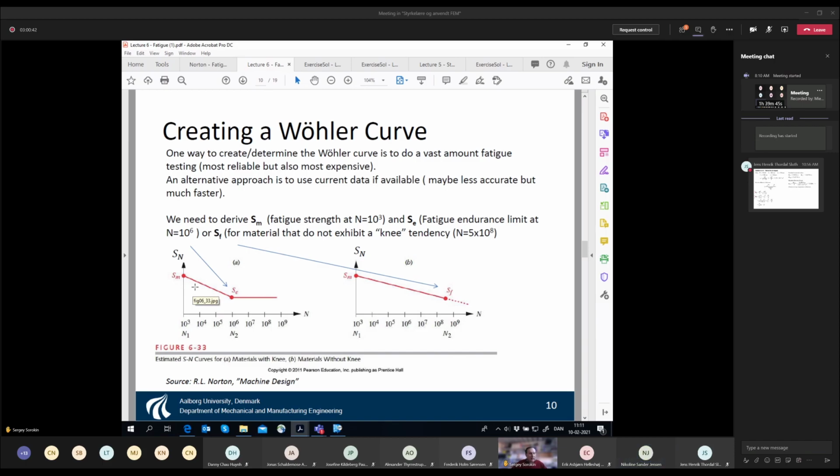So now we make the next step. Let's imagine that we introduce small n1 cycles at this level, and small n2 cycles at this level. If we have a standalone regime with n1 cycles, we have used this amount of its capability. And this is n small 1 divided by n capital 1.